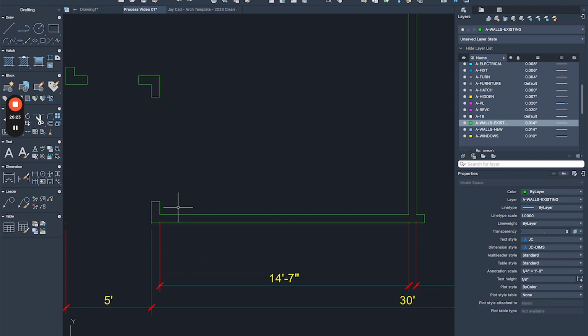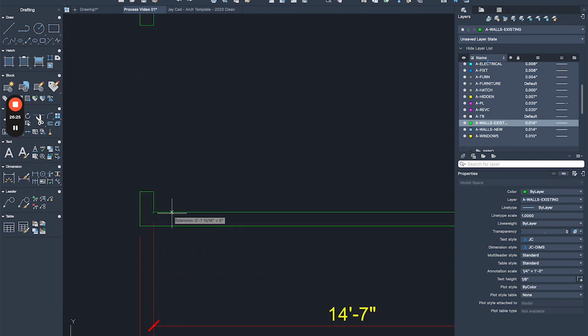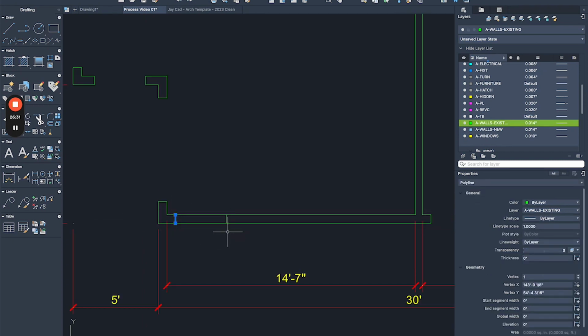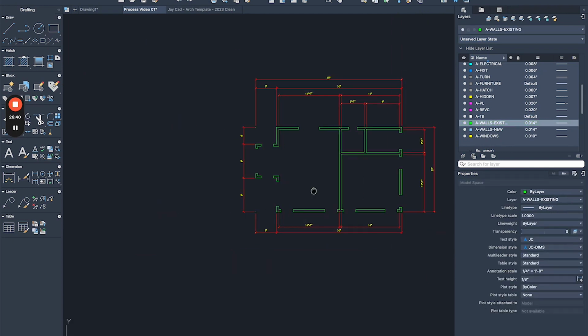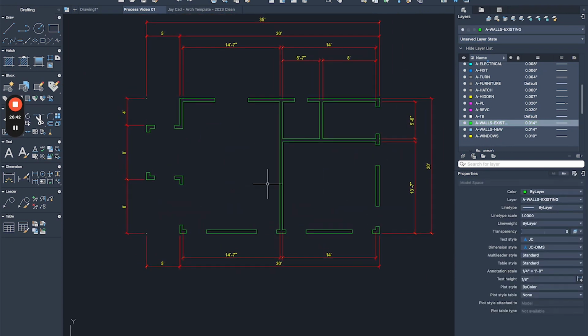And then I'm gonna add a couple windows here. So I'm gonna come here with a polyline. I'm gonna extend 6 inches. I'll do 3 feet wide windows. Okay, then I'm gonna mirror these two beautiful lines from here to here, and then boom, trimming, joining everything again, and this is looking good. And then another save.